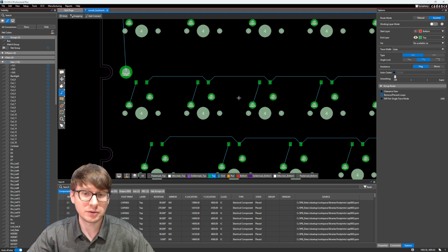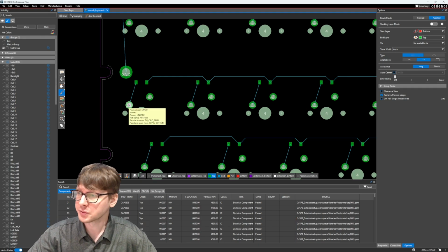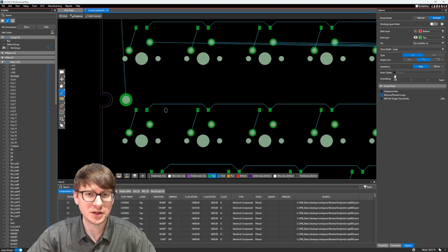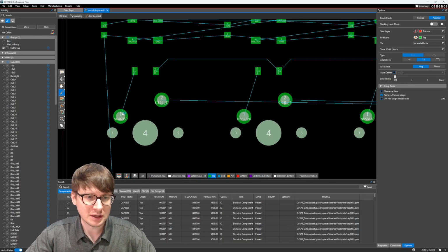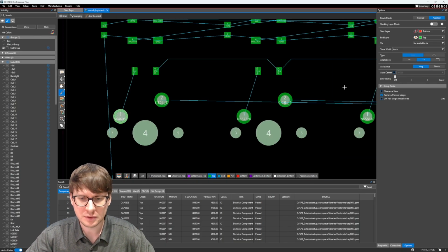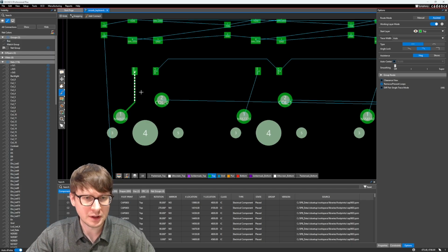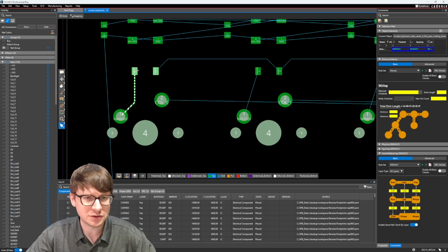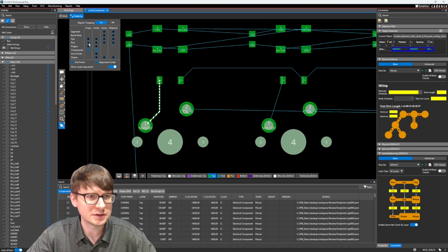All right, so the next thing that we're going to do is connect all of these diodes to the pin on the actual switch. Most likely what's going to happen is I'll do this once, and then anywhere that I can, I'm just going to copy paste it to save time. So we're going to create a simple route on the top layer. Working layer mode's fine. So we're going to create a simple route, and then I will select these traces, and then with my snapping on, I want to snap to pins.